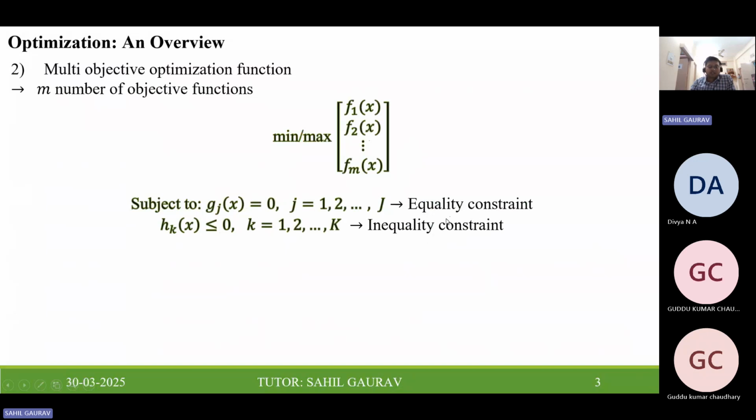When we are having power balancing, then we take it as equality constraints. And when we are having voltage constraints, there should be some range for node bus voltage deviation, or some radiality constraints, that comes under inequality constraints, while power balance comes under equality constraint.